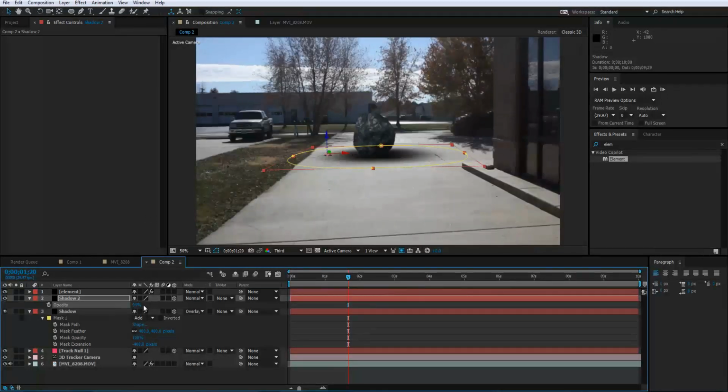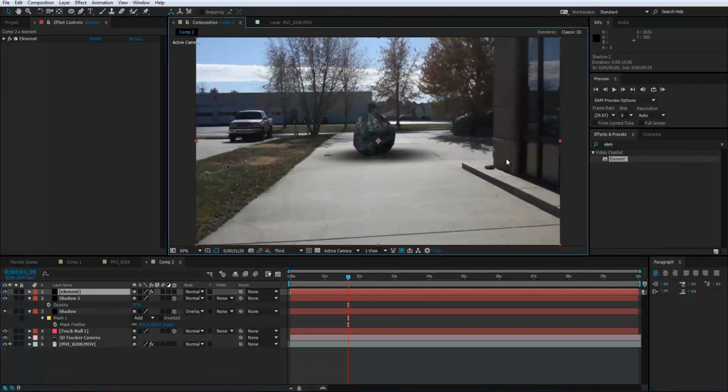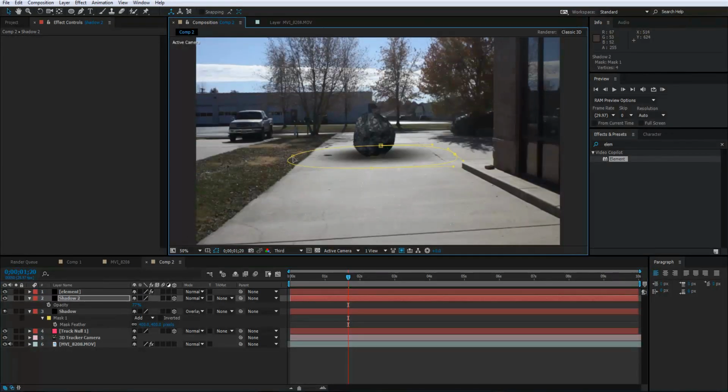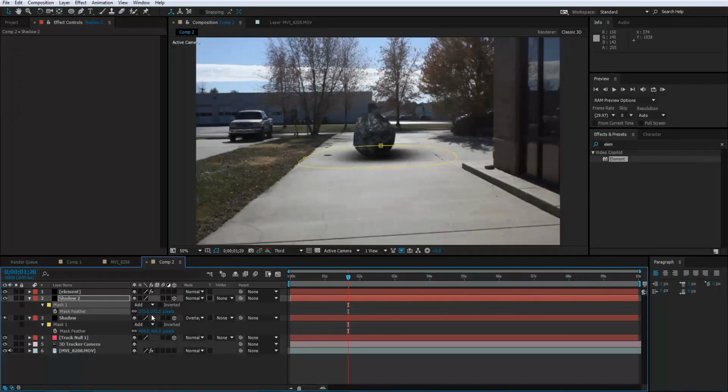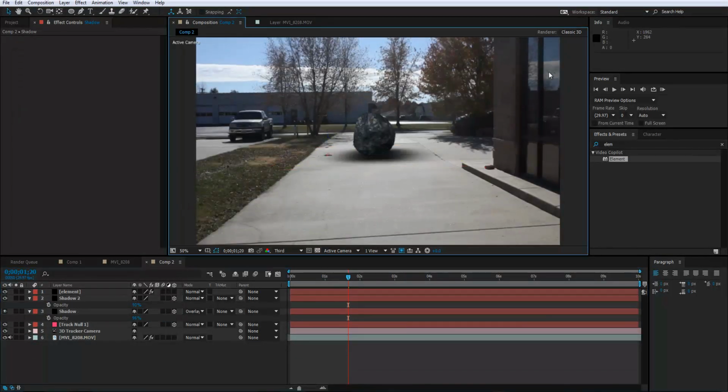All right, about right. We want to match our shadows right back here as much as we possibly can. All right, I'm going to move in my masks some more so I can kind of give this more of a realistic depth to it. Hit F again, change the feather, because the more we move it down, the more of that feather it's going to use. You want to try to match it up to these shadows as much as you can.